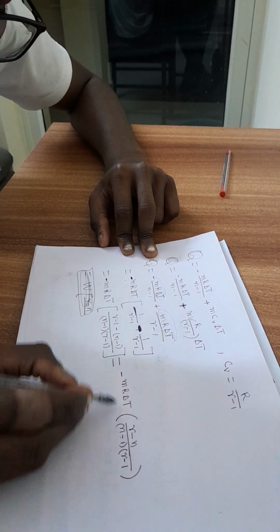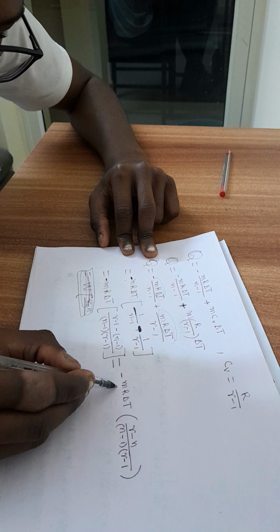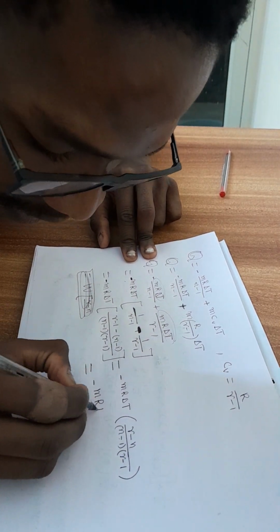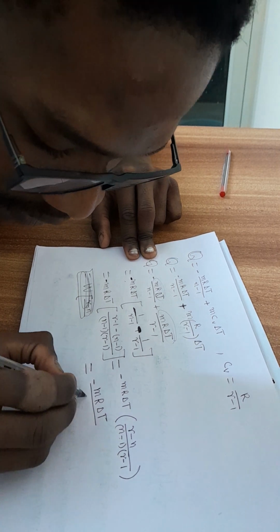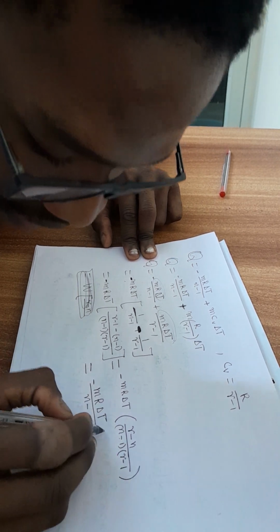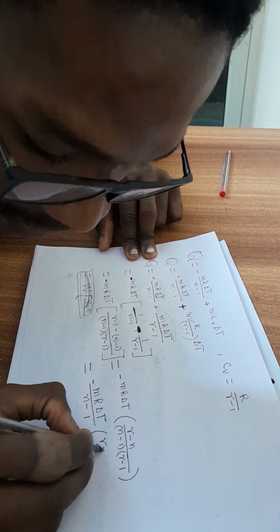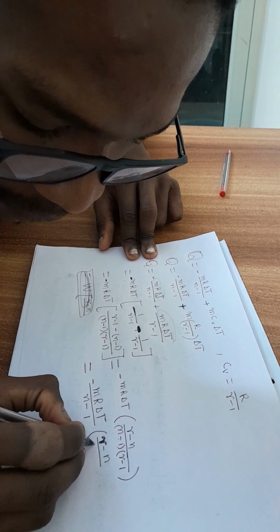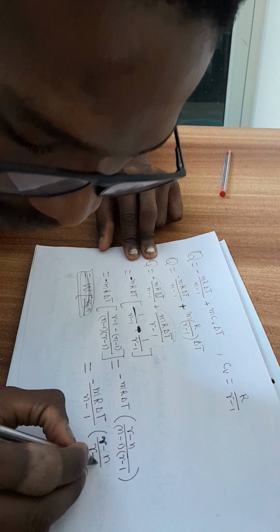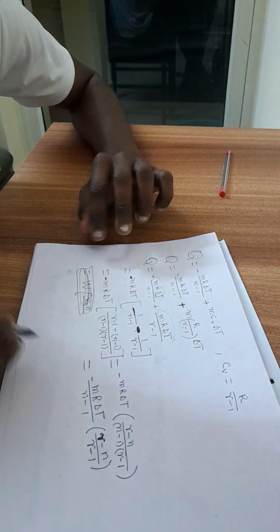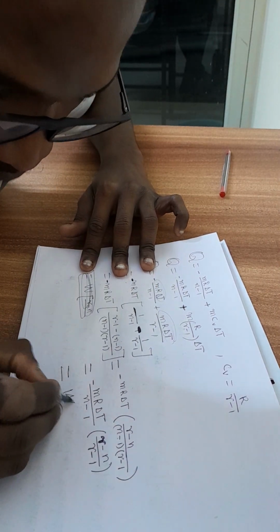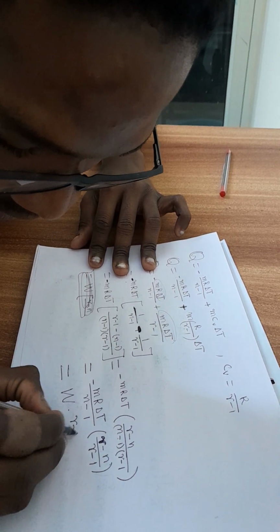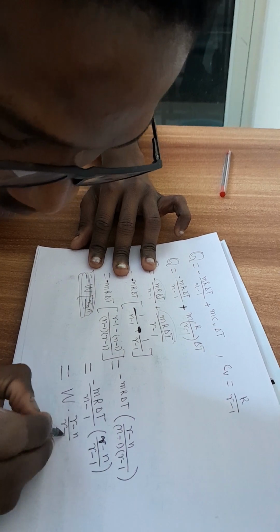So take this n minus 1 out here. So it will be minus mR delta T upon n minus 1, this is work done, and this will be gamma minus n upon gamma minus 1. So this is the heat transfer for the polytropic process: gamma minus n upon gamma minus 1.